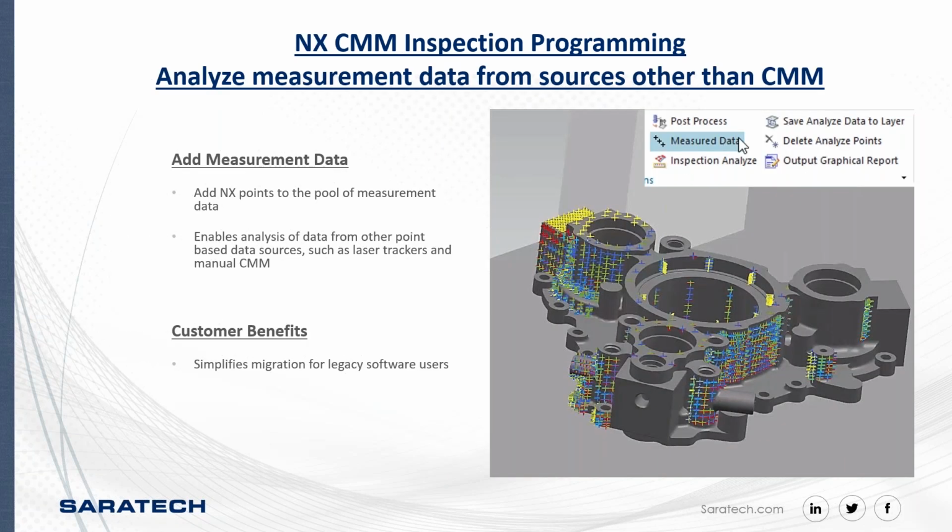Analyzing the measurement data from sources other than the CMM, you can add NX points to the pool of measurement data if you would like to add a point cloud. It enables analysis of the data from other point-based data sources, such as laser trackers and manual CMMs, and it simplifies migration for legacy software users. So your old programs are going to be easily converted into the new software using these methods.